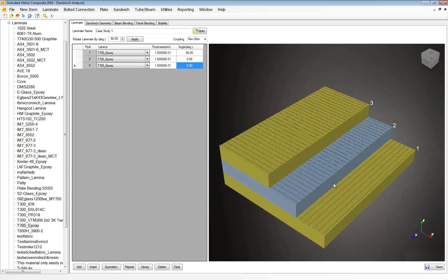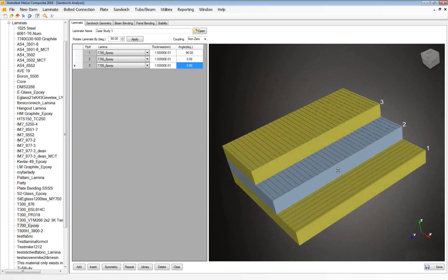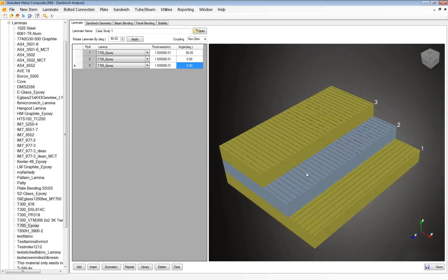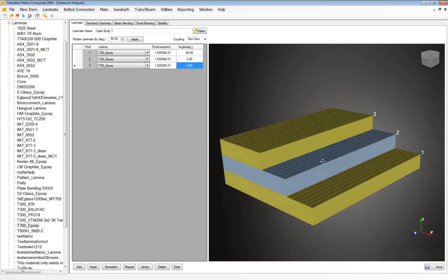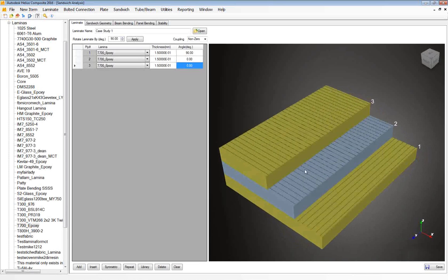This comes into play as a more convenient tool as you increase the number of plies in your stack sequence. So as you have 12 or 20, this can give you a good indication of thicknesses, orientations, and help you catch any mistakes that you might make on the way.